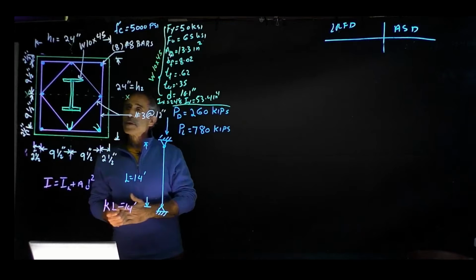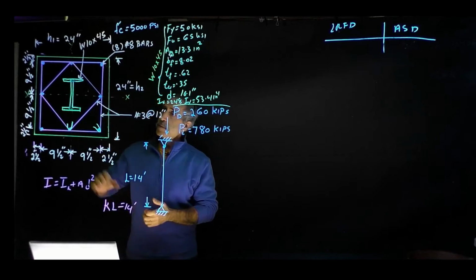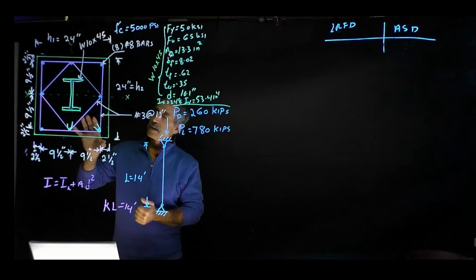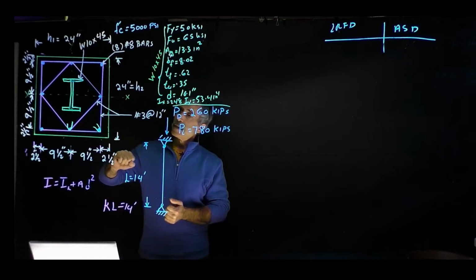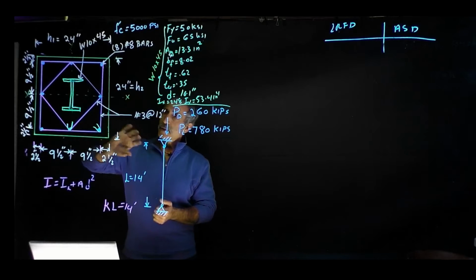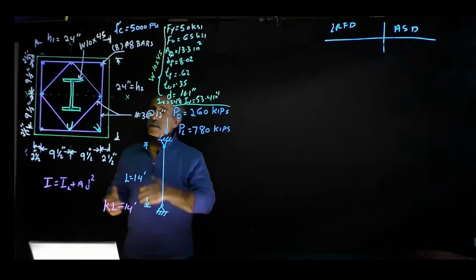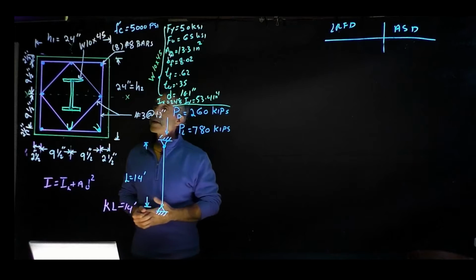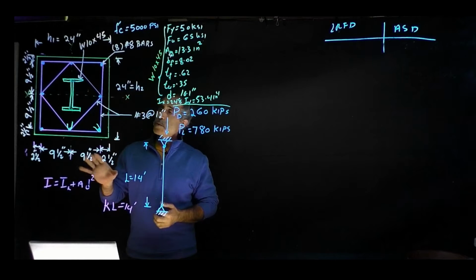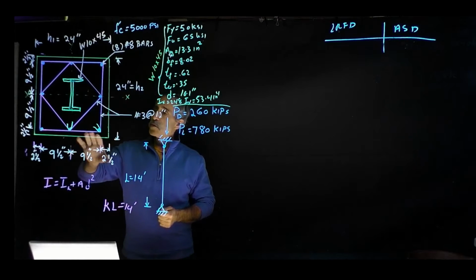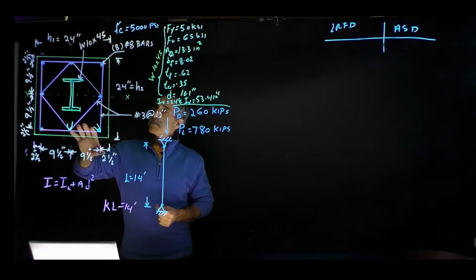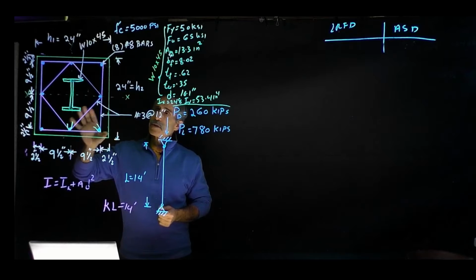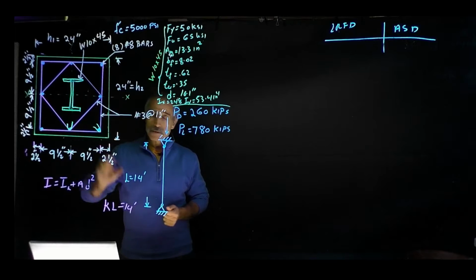Normally, when a designer does a big, tall building design, they probably have a set of standard details. Something like this could be a round column or square column, and they go ahead and use these, and then you can analyze the capacity of it. What we're going to do here, first, is find out if they used enough rebar, and check the spec to make sure this meets the specification.